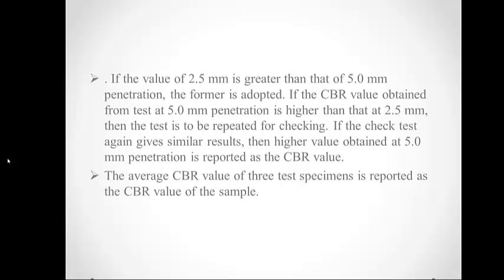If the value of the CBR at 2.5 mm penetration is greater than that at 5 mm penetration, the former is adopted.